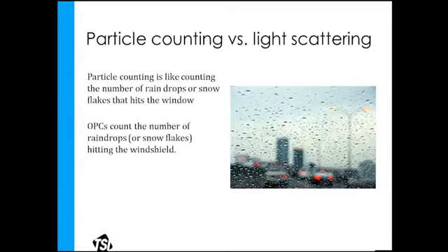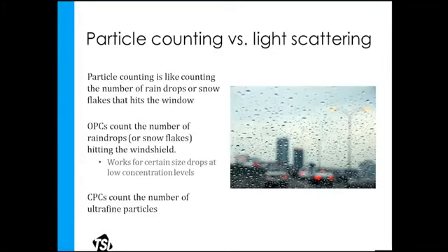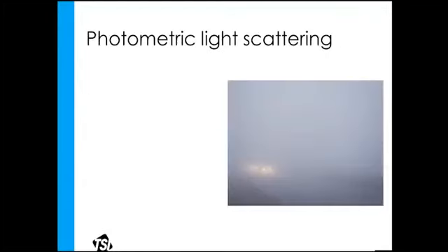It starts to rain really hard, you can't keep up. So higher concentrations in optical particle counters is not the best way to go. They're counting the snowflakes, the drops of rain. It's going to work at certain sizes. We're going to keep up for a while, but eventually, if you're driving too fast, there's just no way. So that's where the photometer takes over.